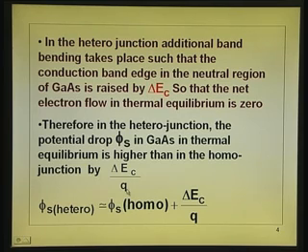So, you can see I can turn off this carrier concentration to 0 practically by removing that extra band bending, that is, by applying a forward bias voltage across the junction equal to delta E c by q. Please remember this when you go back to the HEMT discussion, because you should know how much voltage you must apply to the gate to turn off the device, and when a junction like this comes, this is the amount of voltage that must come across the junction.